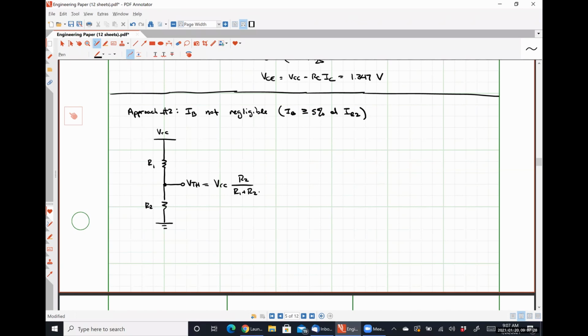Now I also need to find the Thevenin equivalent resistance seen. So remember that finding the Thevenin equivalent resistance means looking into a dead network, which means that all of our voltage sources are shorted out, turned to zero. So our network is going to look like this. Here's R1, here's R2. We're looking in to that node and we're finding, sorry, not Rn, getting things confused with earlier.